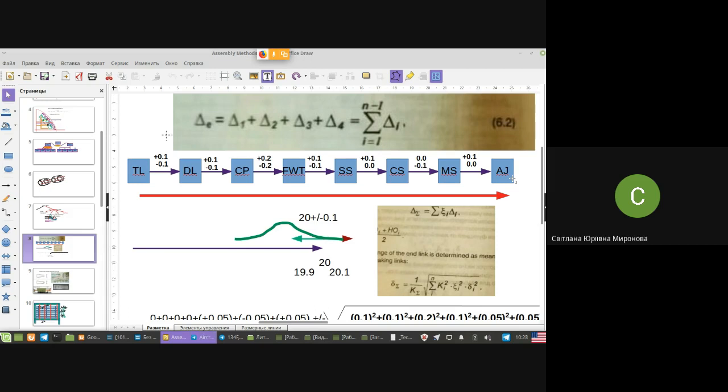When it was about assembling, mounting of the jig by the mounting standard in laboratory work, it also was obvious, because it was explained, and because you know that the assembly jig was made by the mounting standard, which was made by the counter standard, which was made from the surface standard. You see, I'm moving backward a little bit. The surface standard in turn was made from a framework of working templates, and the templates appeared from a system of lofts. So the history of this object you know, and how to calculate the error of this jig, the error of this object, is not difficult.